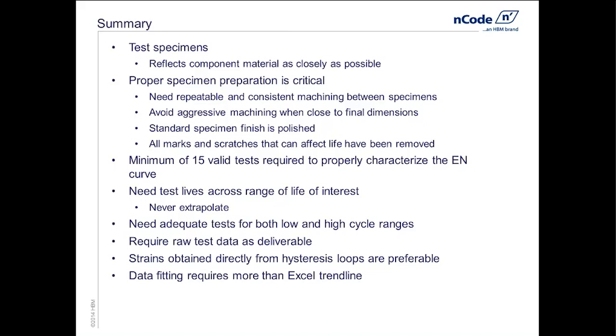But in most cases, they will have captured the hysteresis behavior and have measured values for elastic and plastic strain as well. And you want that data. Again, you need to understand the range of the data to know where you can and can't use this curve. Again, strains obtained directly from the hysteresis loop are preferable.